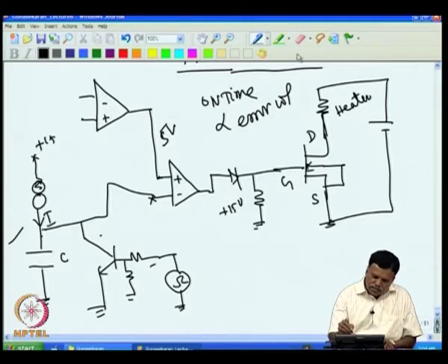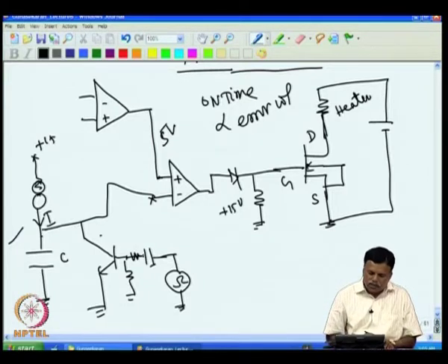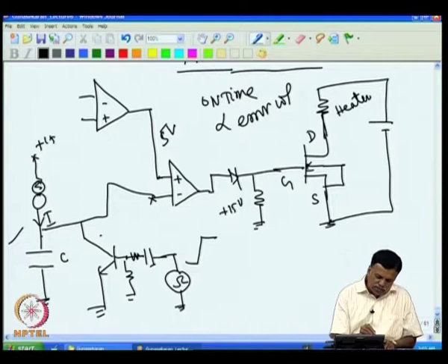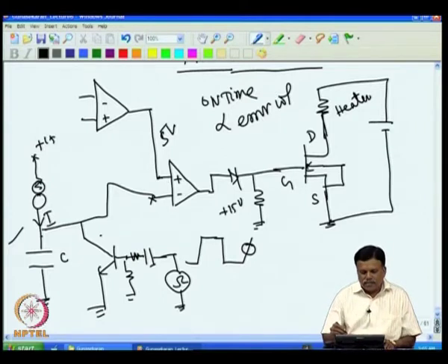During the rise time it has to discharge, so I put a resistance to limit the base current. Whenever this rising edge comes, a plus voltage comes here and it discharges, and the rest of the time it keeps charging. The next pulse comes again at the rise time, it discharges once, and then again slowly rises. This way the heater on-off time can be controlled.